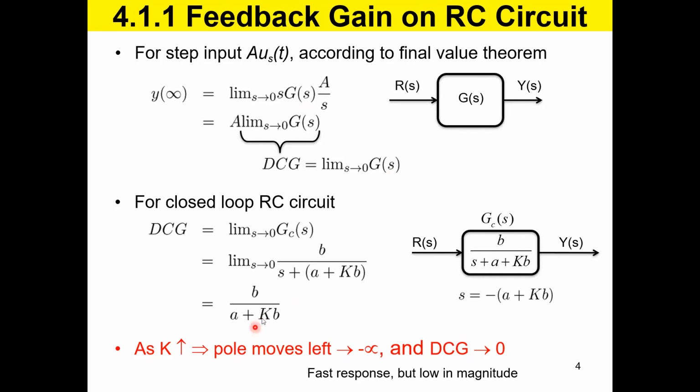So there also you can see K here, right? K is the feedback gain, and it is there in the feedback in the DC gain also, which means you can control the DC gain by changing K. So we are going to exercise some degree of controls here through this K. By changing K appropriately, now we can exercise some controls on the plant.